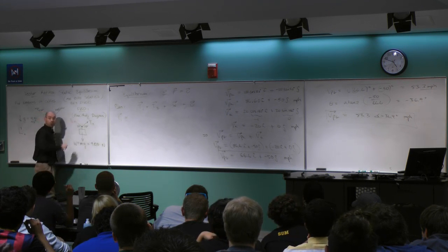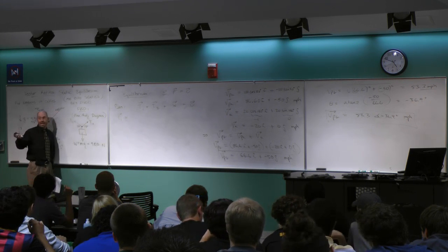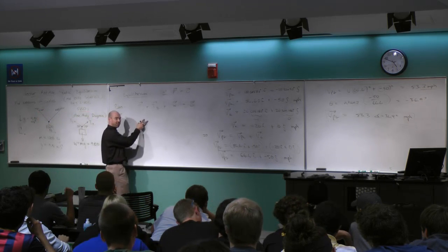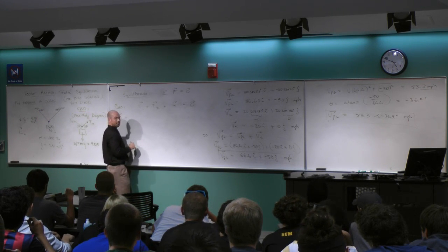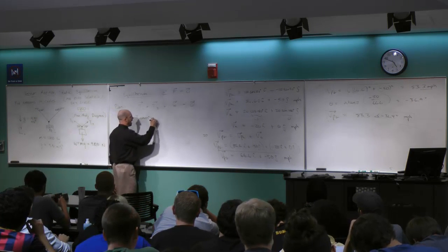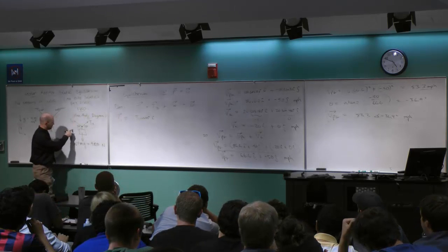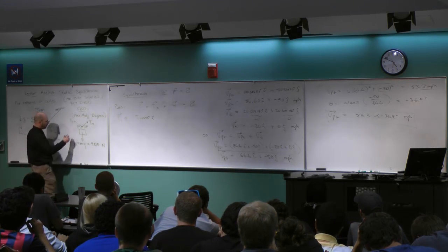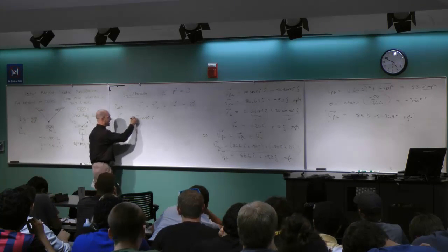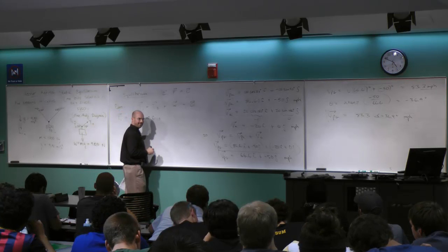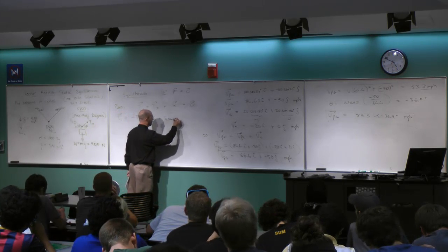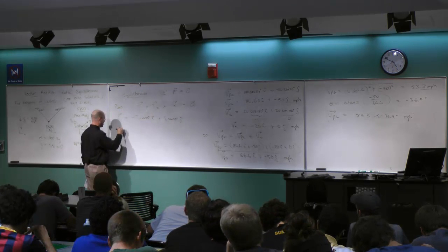But this way, I want to write these down. T1 is unknown. So when I write the vector down, I can have unknowns right in the equation, right? So if T1's the hypotenuse, then the x component is T1 cosine 45 degrees i. Is this a positive number here? No, this guy's going left and up, right? So this is a negative, plus T1 sine 45 degrees j. So that's T1.